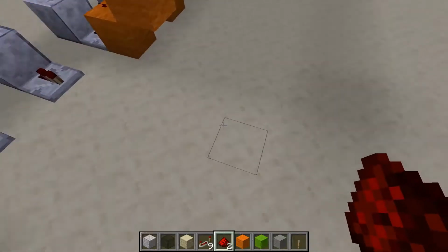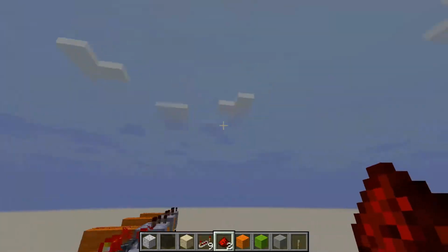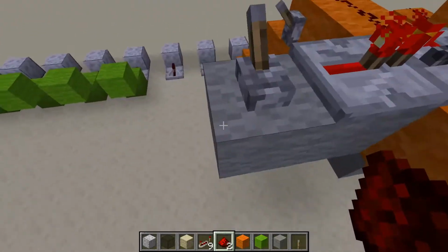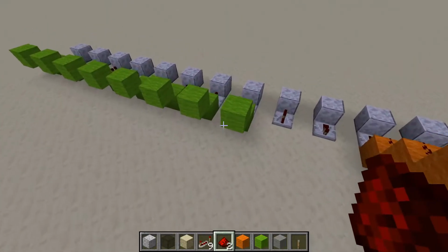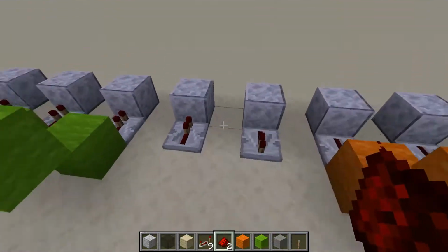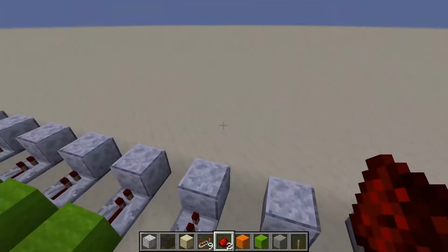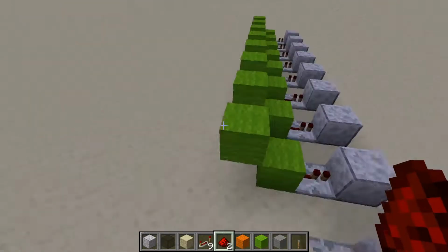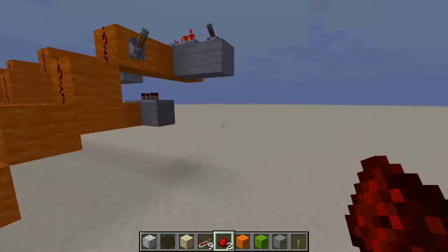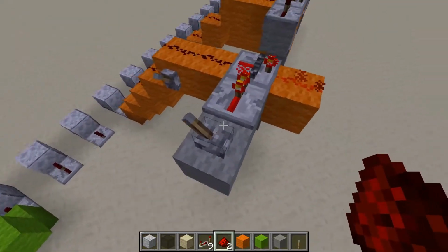So what we're gonna do is build a NOR latch that keeps the save bit high until the tape drive replies, "Yup, I have found the value of the address and outputted it through the output bus, and have told the PC that I am outputting through the address bus." At the moment that this bit lights up, it will also activate the NOR latch to deactivate the save.